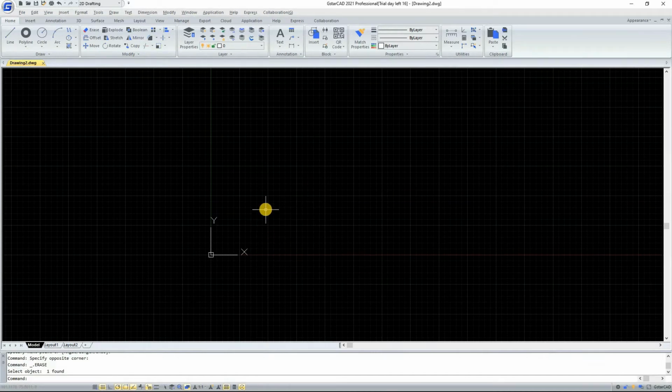Now I will explain how to set up and edit units. One thing I recommend is drawing with the scale of 1 to 1. I mean, if you want to draw a line with 1 meter of length, draw it with the real length and not with 1 centimeter, for example. That's because it's easier to not get confused, and you only need to scale the drawing when you plot it. Now, if you look at the bottom left corner, you can see the coordinates of the mouse pointer.